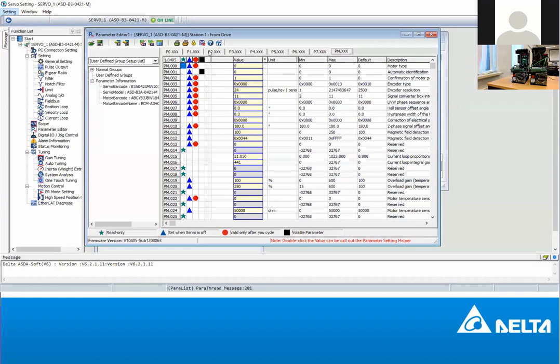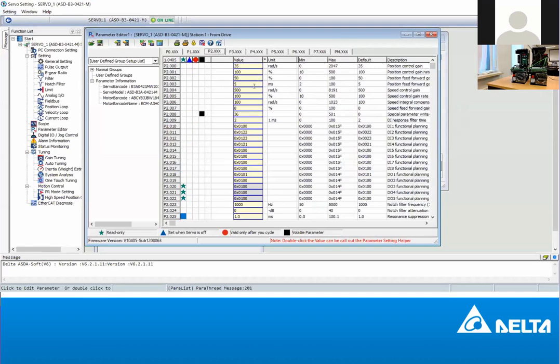So let's go to parameter 2. You click here, parameter 2. We set parameter 2008. Now you can see the value I have here is 36. We want to write it as 10 to reset it. Also, try to observe the video if there's a response from the digital display. You can see it's busy, done. I hope you saw that. So now it's 10. We have successfully written.